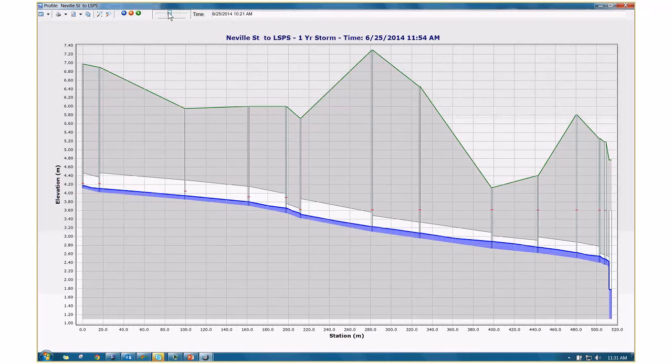Can you see? You can create dynamic profiles, and you can then compute your profiles. You can check how much water is being filled in the network, how the catchments are contributing flow in your network, right? Now it's a bit slow, but you'll appreciate it when it approaches 11 a.m., because that's when the rainfall really occurred, right? As you saw, it was midday rainfall. Can you see the water levels changing dynamically?